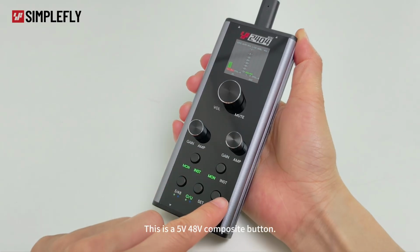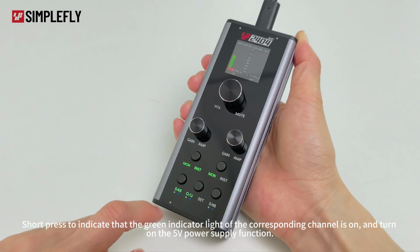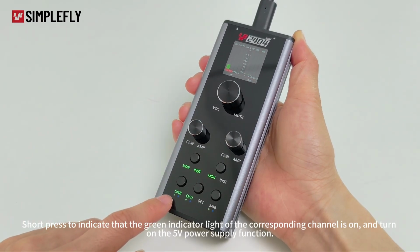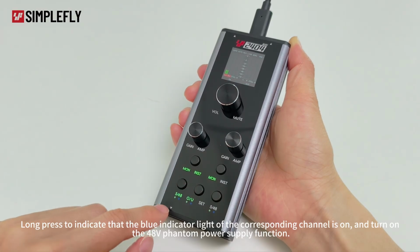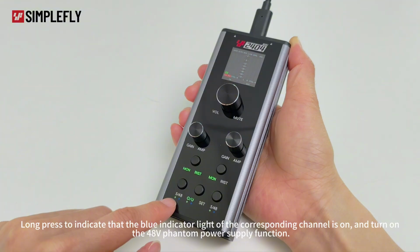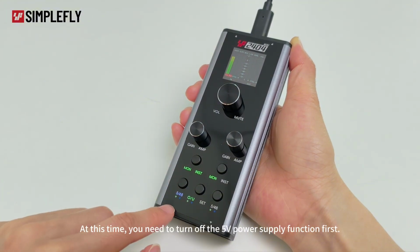This is a 5 volt 48 volt composite button. Short press to indicate that the green indicator light of the corresponding channel is on, and turn on the 5 volt power supply function. Long press to indicate that the blue indicator light of the corresponding channel is on, and turn on the 48 volt phantom power supply function. At this time, you need to turn off the 5 volt power supply function first.